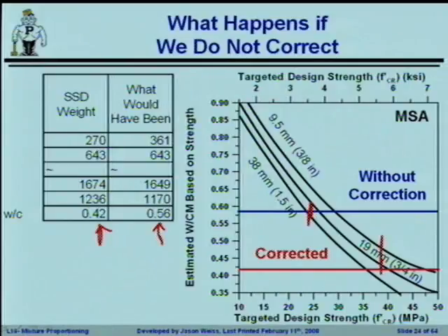So a lot of times they're actually going to be pre-sprinkling the lightweight aggregate so that it's not absorbing water out of the system or it's not giving back a lot of water to the system. But you would see huge differences in your strength and huge differences in your slump. And one of the biggest things is if you go to a place that's having problems with quality control, one of the things that they're usually doing a real poor job on is controlling the moisture in their aggregates. And they're just getting a lot of excess water in the system. So they'll have their strengths bouncing around, the workability of the concrete bouncing around out in the field. And typically the best way to fix that is to come in and do a little bit of process control on your aggregate.